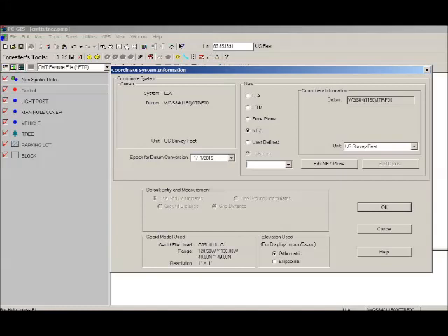When your engineer gives you the image of a drawing of your land parcel, it has no geographic meaning. To place such a drawing in your PC-GIS software program, you could first establish a few control points, and then use the geo-referencing function to register the image. You can then load the registered image into the software, and use it as a background for additional work.